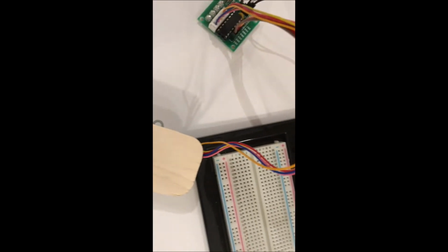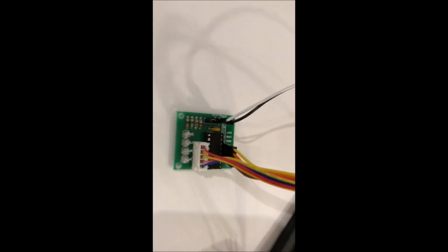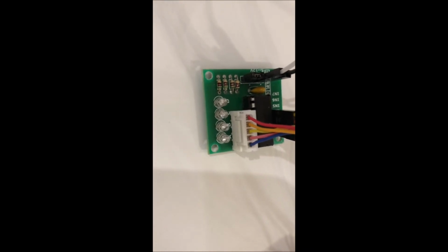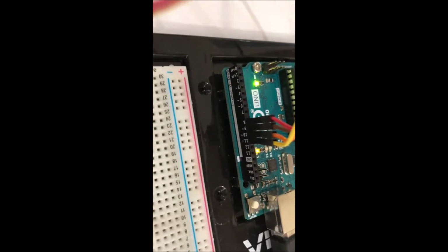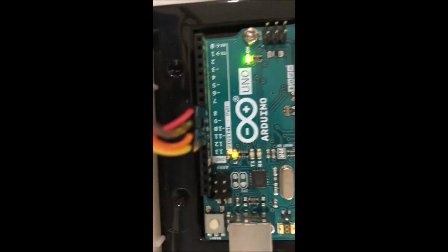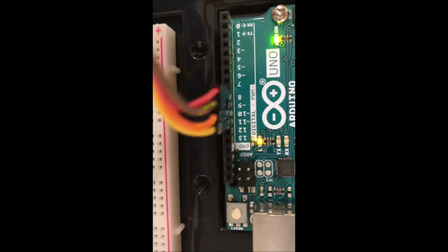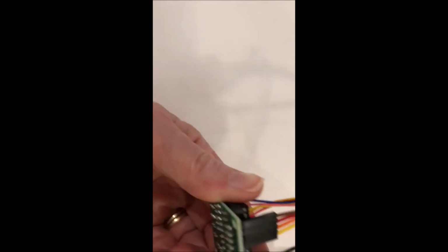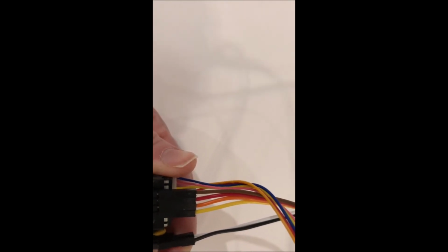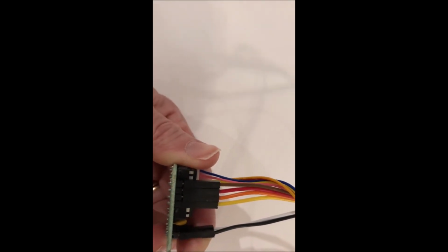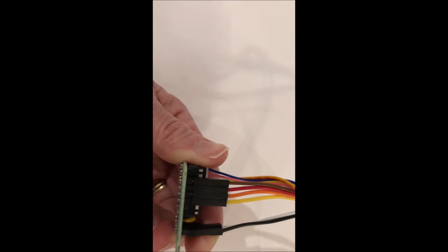Then I've got my wires coming over here for the motor, and they're supposed to match up with these pins over here on my board, okay? And they're supposed to go right down in order. 8, 9, let's see, red, brown, orange, yellow. And I'll come over to my board. Uh-oh, brown, red, orange, yellow. So that might be the problem. Let me swap those wires and we'll try.